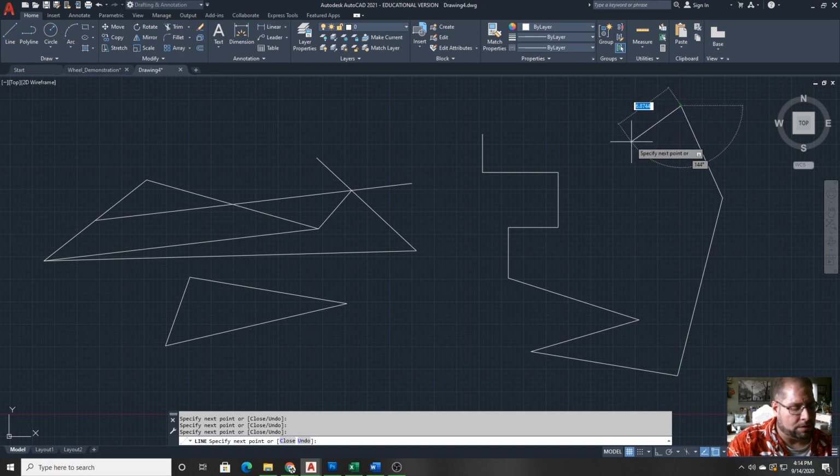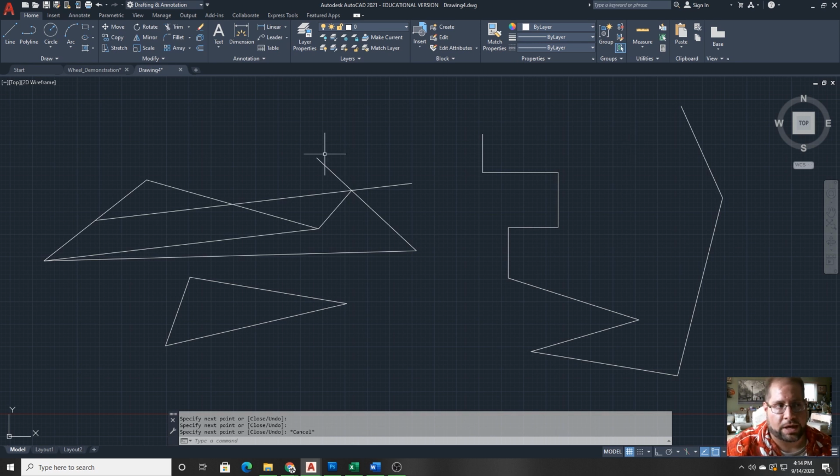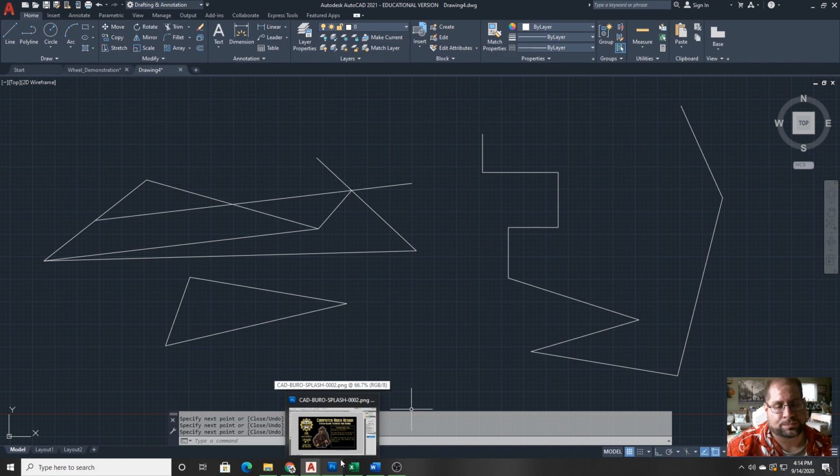So I think you've seen, again, drawing a line, choosing the command by using the keyboard, line being a very, very special command with a one-letter shortcut to it, the ribbon location of the line, as well as me showing you choosing points on the screen with a mouse, using object snap on the screen with a midpoint snap, endpoint snap, and intersection snap, ortho mode, and also the context sensitive options that come up in the middle of the commands. Thank you.